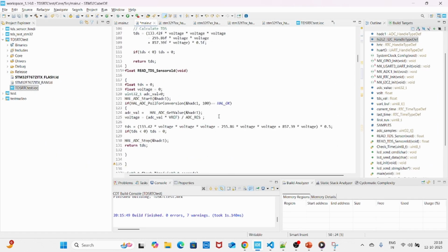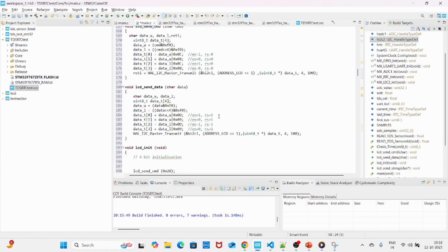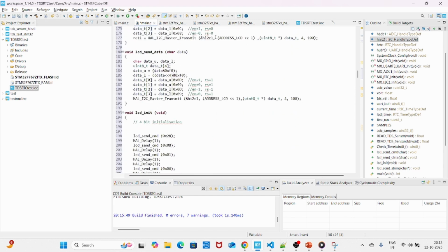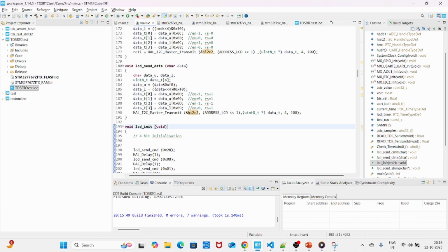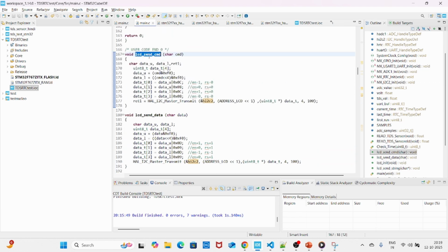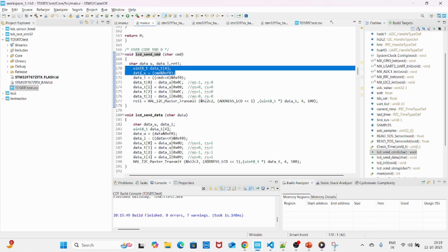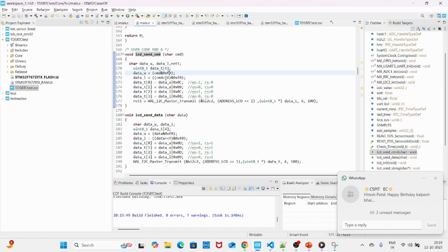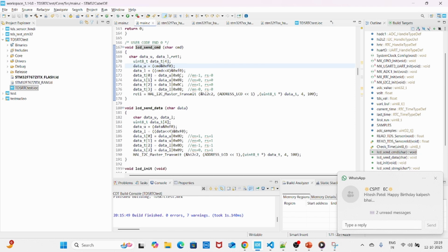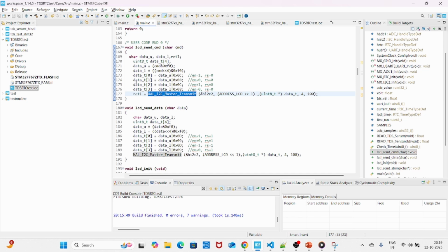Okay. So let us reopen this code. Check where I just copied that function right here, and here I have to change this from I2C1 to I2C2, right? What this function will do, in this whole part, you can see in LCD command also we have some command. That command will first mask the upper 4 bits, then it will mask the lower 4 bits, shift left 4 times, and then it will simply write that on this function, provided we have this configuration, you can say enable 1 to enable 0, right.